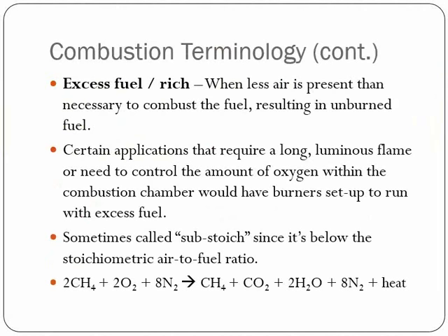So that's a desired effect, especially for processes where you're doing some kind of metal coating that has a rapid oxidation, or it's highly corrosive. You do not want that oxygen to interact with the product. You would run your burners with excess fuel or run them rich to control that reaction from occurring on your process.